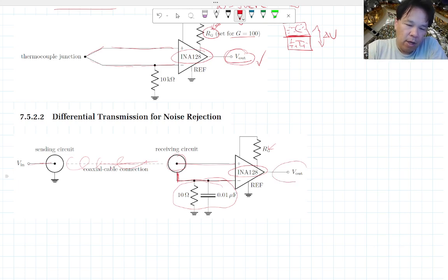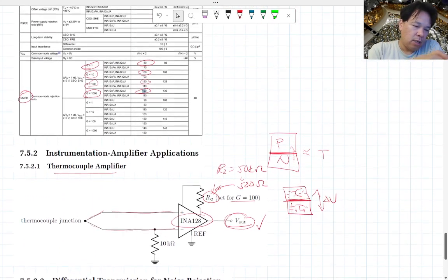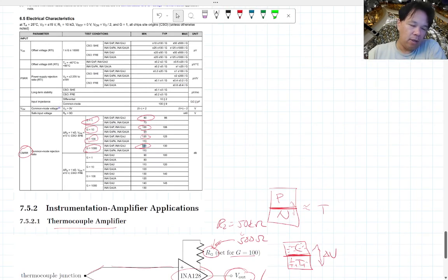So what happens is you're amplifying this output so that your television will have sufficient signal, amplified in order for it to detect and relay the information that it needs. Oh, your cable modem, and we're going to talk about modems in the future pretty quickly. Okay, so these are some of the applications that you'll see with differential instrumentation amplifiers, and these are typically the ones we actually use in a lot of cases because we don't want to go into the nitty-gritty of matching the resistor values and stuff like that.